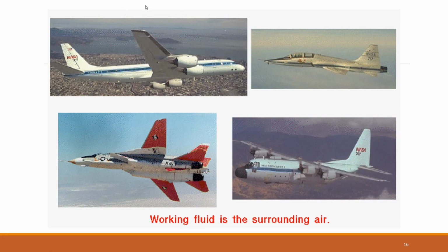At the upper left of the reference slide is a DC-8 airliner designed to carry large numbers of passengers or heavy cargo over long distances at high speeds. Because it spends most of its flight time cruising efficiently at altitude, it uses 4 high-bypass turbofan engines. In these engines, a large fan at the front moves a substantial volume of air around the core engine, providing efficient thrust and reducing fuel consumption, ideal for commercial aviation.